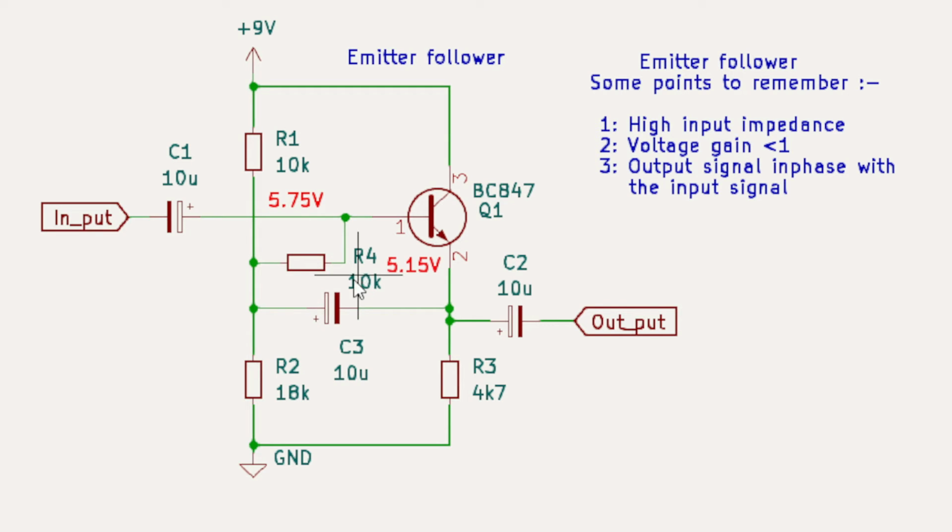So now what we're doing is we're isolating the impedance of these two, which of course is the 10k and the 18k in parallel. The reason that you treat them in parallel is the power supply from this point to this point is considered to be a big capacitor. So AC wise, this point is connected to that point. So those two become in parallel. And so the impedance at this point is 10k in parallel with 18k in series with 10k. So we'll just think about that for a minute.